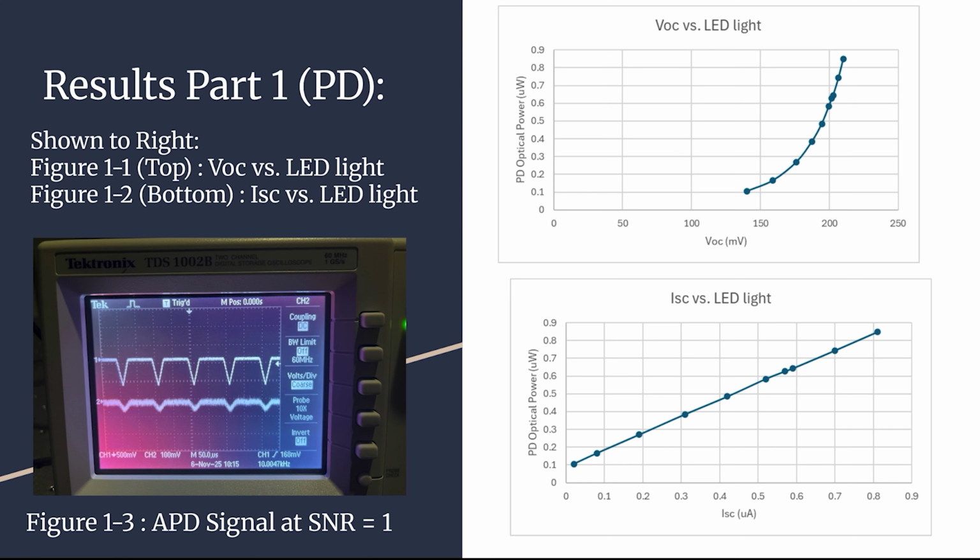For the photoconductor, the measured voltage rose slightly with light intensity but followed a non-linear trend. It responded more strongly at low light levels and began to saturate at higher intensities because the device resistance decreased toward the limit set by the series resistor.